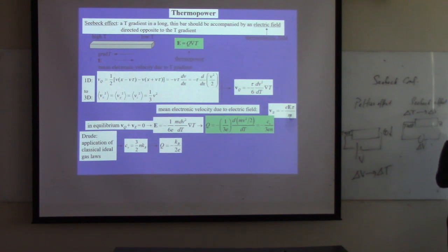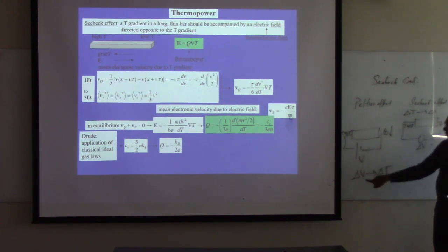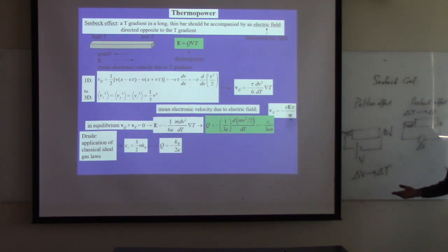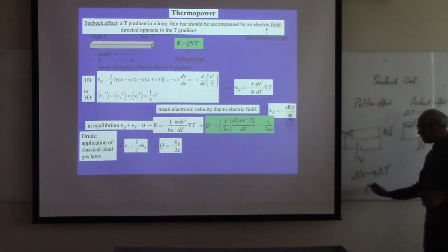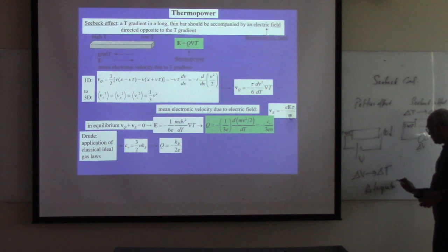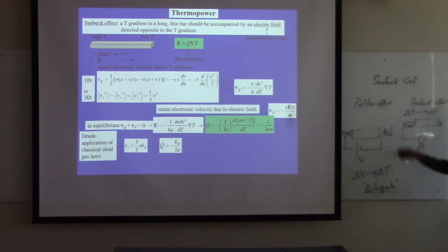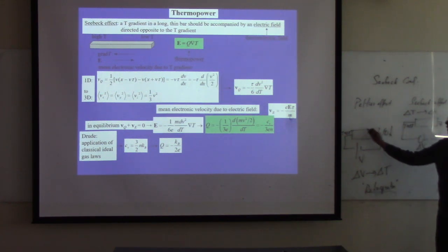If I connect it to a power supply, I can make one end very cold, even as cold as ice temperature with like 5 volts. So you are giving voltage and making delta T. What is that basically? It's a refrigerator, right? There are already commercial refrigerators based on this thermoelectric. So this material is very important. We call it thermoelectric material.